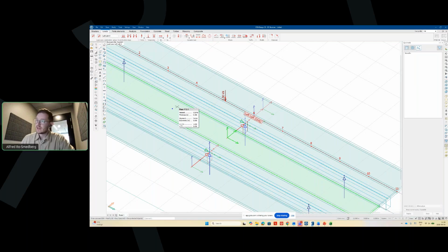But I think an easy way to do an estimation is to think of it like this. You multiply the runtime of one result by your total number of cases, and you can estimate the total runtime you will have in the end. So when you optimize for your running time, you should use just one load case, and you should play around with the mesh. You can play around with the fineness of the optimization algorithm and also these grid options. So that's what I'm going to be showing you for the rest of the webinar.